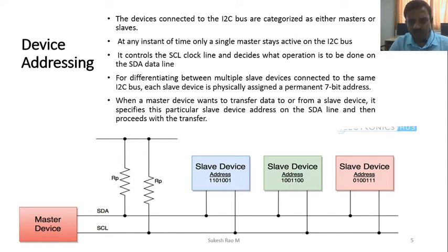There is another device here whose address is 4C hex. 4C is the slave address, and here it is 27. So this is 27, this is 4C, and this is 69. These are different addresses. Whenever you want to communicate, you need to assign certain values here, the address.